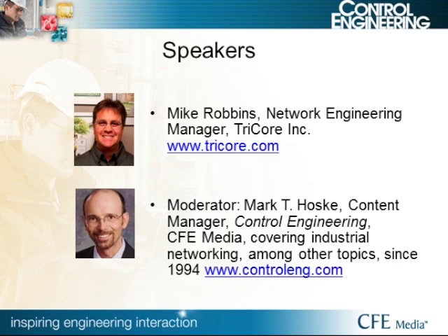And then Cat5e versus Cat6, I wouldn't recommend using Cat5e at all anymore in the industrial environment. I would use at least Cat6 or better. In fact, a lot of Cat6 cabling now, the cable manufacturers kind of skipped to Cat6a, improved it, and took those old Cat6a type cables and are actually using them as Cat6, so they're backfilling that category. There are very good cables, so I would recommend at least Cat6 and maybe even Cat6a if you're putting in new cabling.